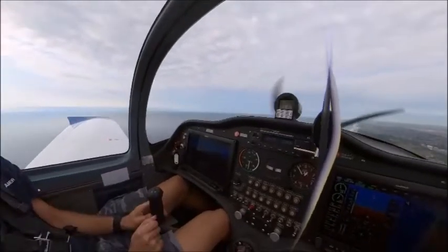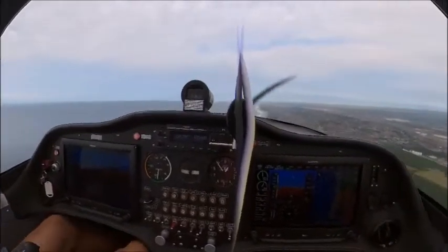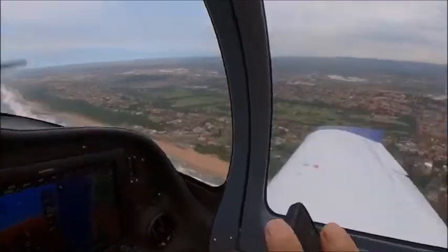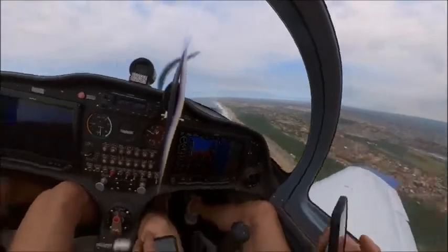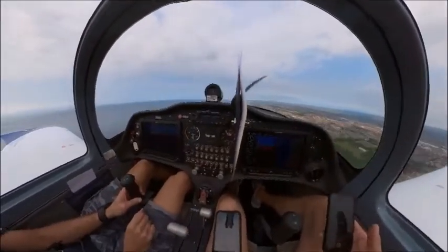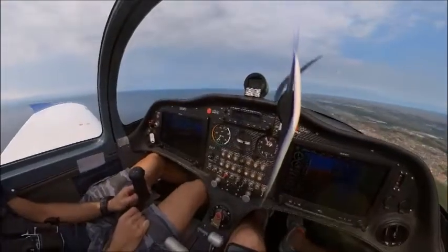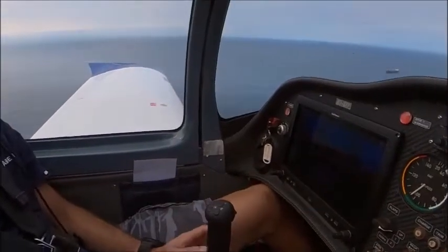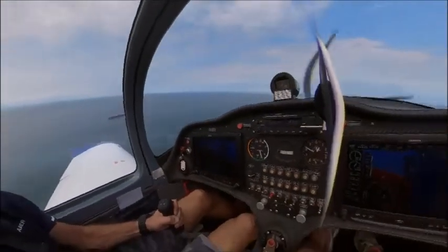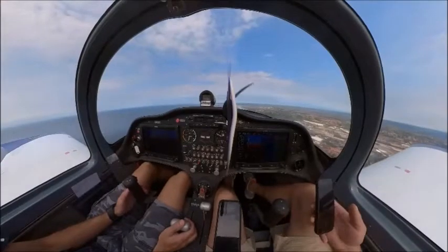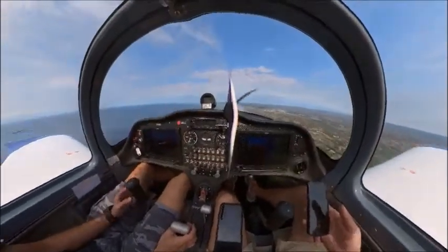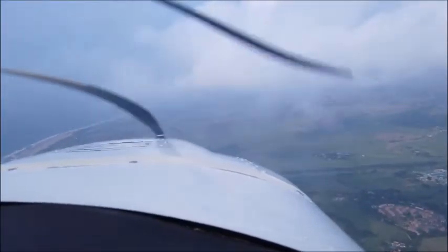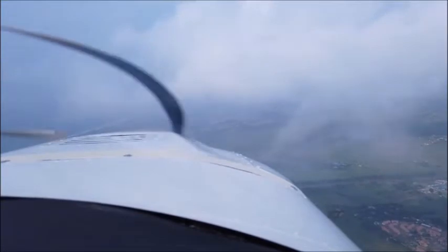Okay, so we're busy going southbound from the harbour entrance. At the moment we're flying at 1,000 feet in altitude. So in aviation, all your vertical heights are always in feet, while your distances away, from one point to another, would be in meters. We always have to repeat and notify other aircraft of our location, whether we're above or abeam of a certain point. And we've got to always give our intentions of where we're going and what height we are at.